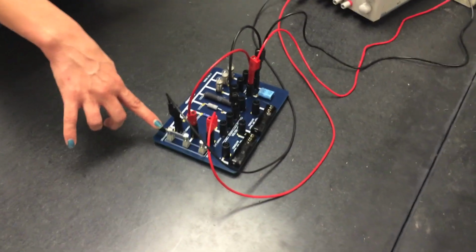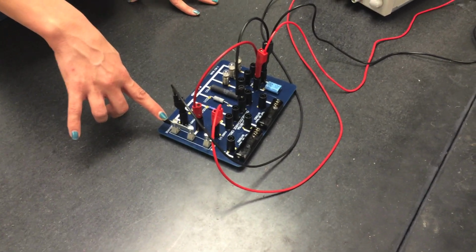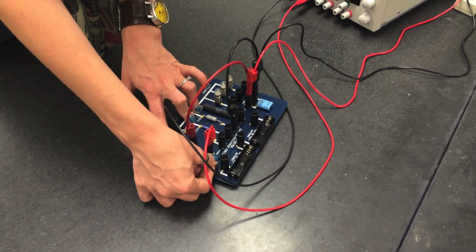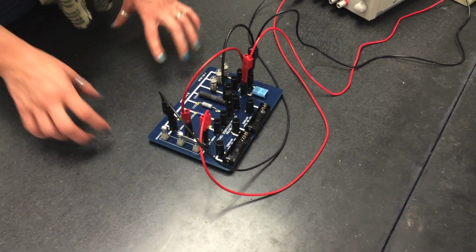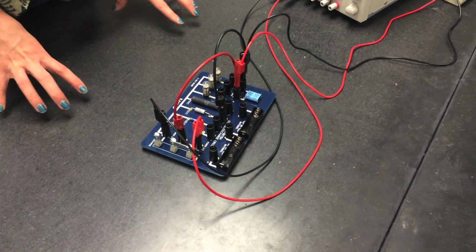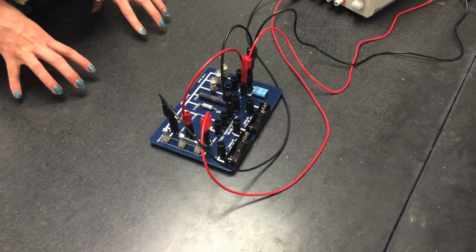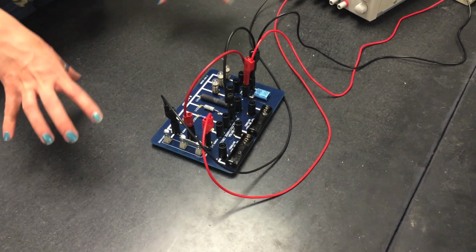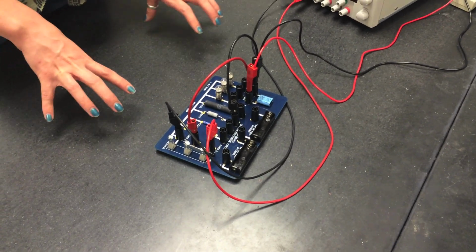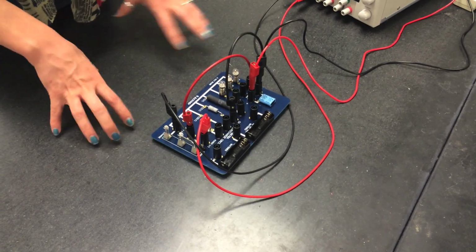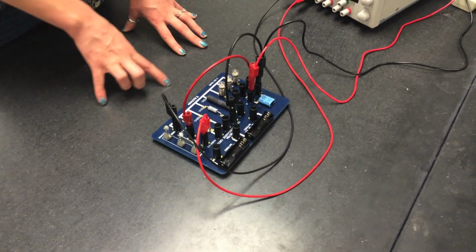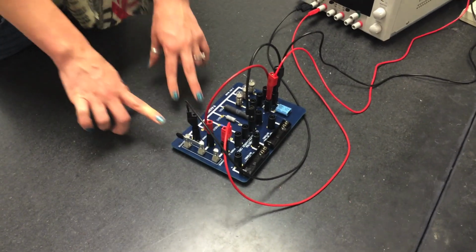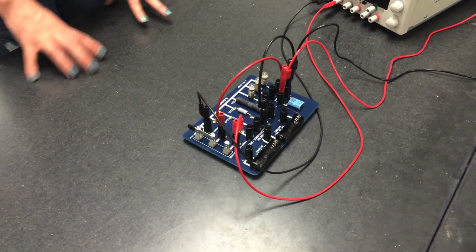You're on discharge, press start for the data collection, then wait 5 to 10 seconds, and then move the switch to charge. Wait until the data collection is stopped by Data Studio. That's 200 seconds. Once you're done, press start again, and again wait 5 to 10 seconds, so the voltage now should be at the maximum, and then turn this to the discharge position and wait until 200 seconds is up.